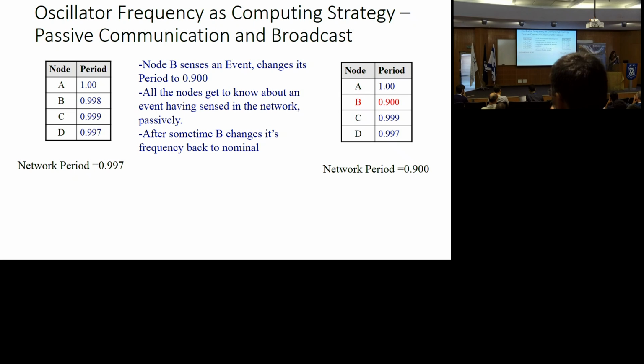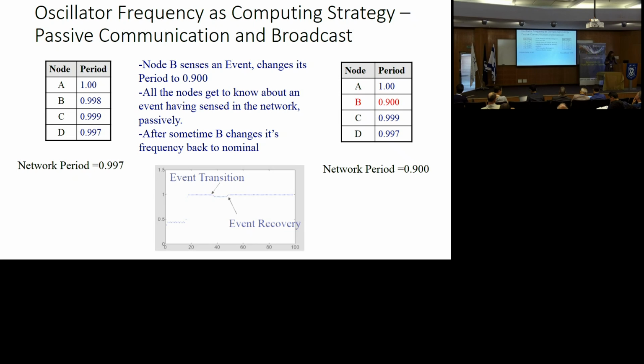One last thing I'm going to mention, maybe my next to last slide: I am very interested in these coupled oscillators as a means of communication and clocking networks, but they can also be used to communicate analog information. What we're showing here is that if we take a set of nodes that all have their originating frequency, but one of them is faster than the others, maybe one in the middle that we make much faster, then because of this characteristic of the network, all of the other oscillators will follow that one. All of the oscillators take on the frequency of the fastest oscillator.